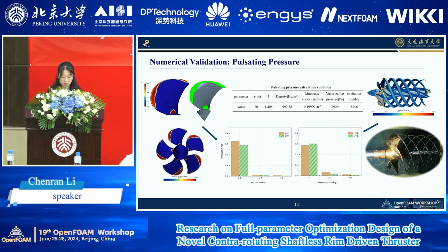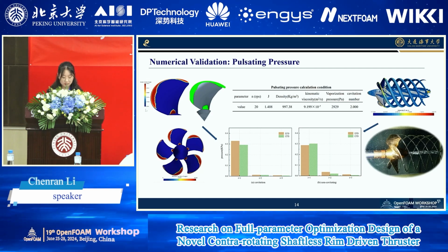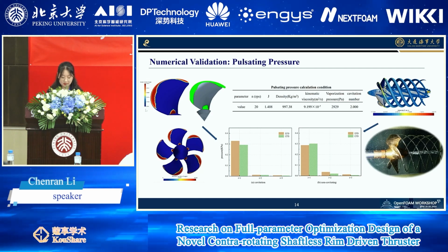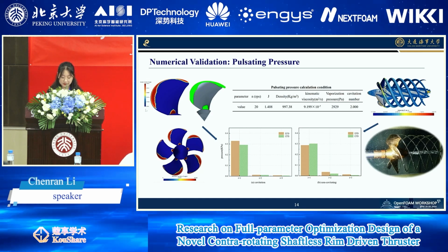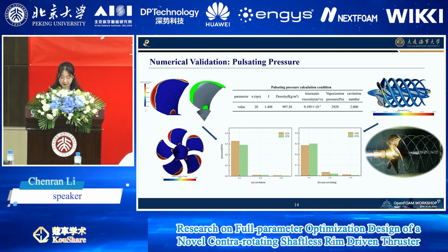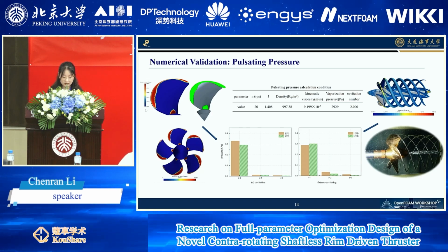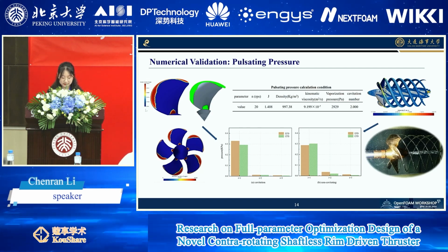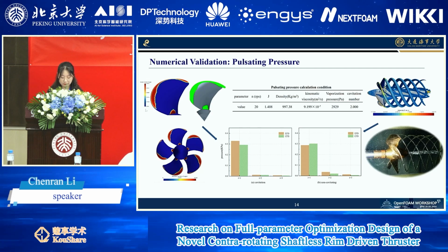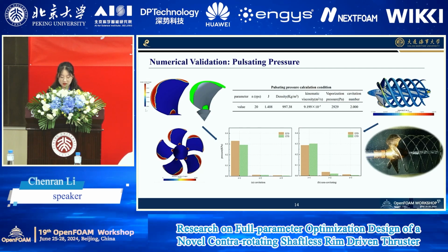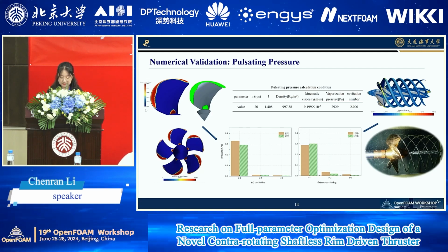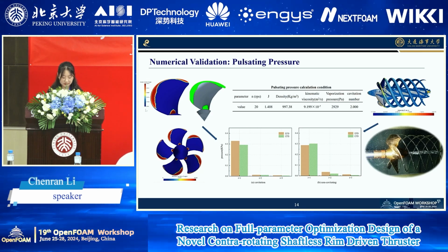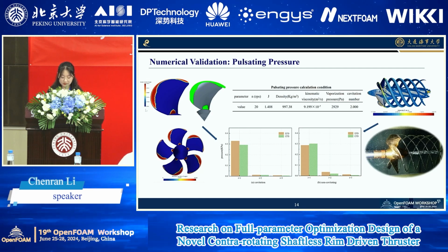detection results at point P2 obtained from the above setting with the experimental values of case 3 provided at the 15 SMP conference. The figure shows that regardless of whether cavitation occurs, the pulsating pressure amplitude at the first blade frequency is significantly higher than at the second frequency.